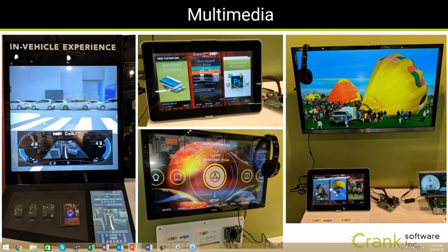At Embedded World this spring, we presented 2 demos, the connected oven and kiosk. Both of those had the Snips voice recognition software, so we're leveraging the power of the i.MX 8M hardware to handle voice recognition and translating voice commands into logic that you can use at runtime. The oven used the voice framework to listen to voice commands.